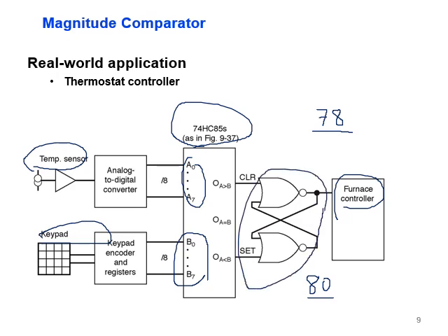Here we put a latch just to send the output signal. We'll talk about latches in the next few topics. If the temperature B, 80, is higher than the number A, which is the temperature sensor of the furnace, then we send a signal to the furnace control to increase the temperature. Let's say it increases up to 80.